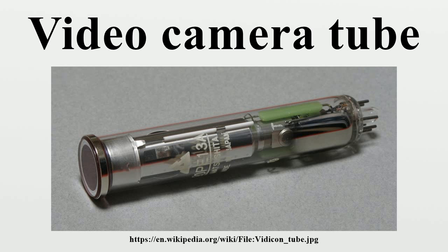On the other hand, in 1934, Zworykin shared some patent rights with the German licensee company Telefunken. The image Iconoscope was produced as a result of the collaboration. This tube is essentially identical to the Super Emitron, but the target is constructed of a thin layer of isolating material placed on top of a conductive base. The mosaic of metallic granules is missing.